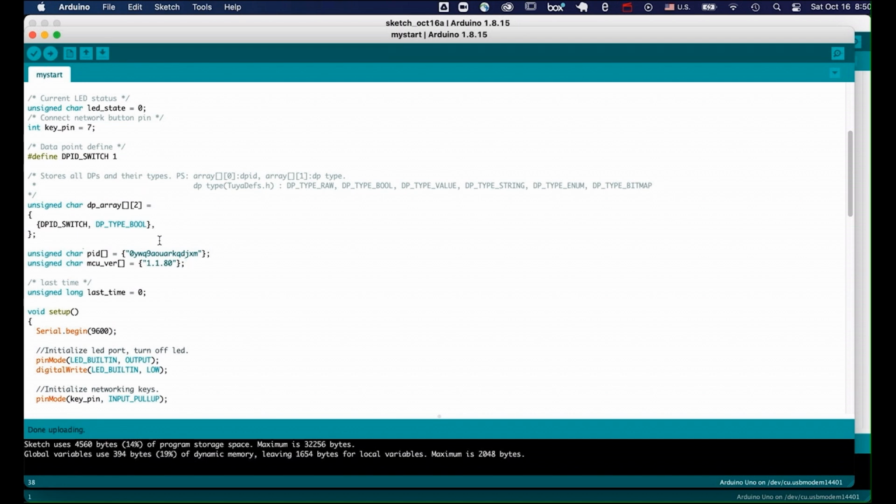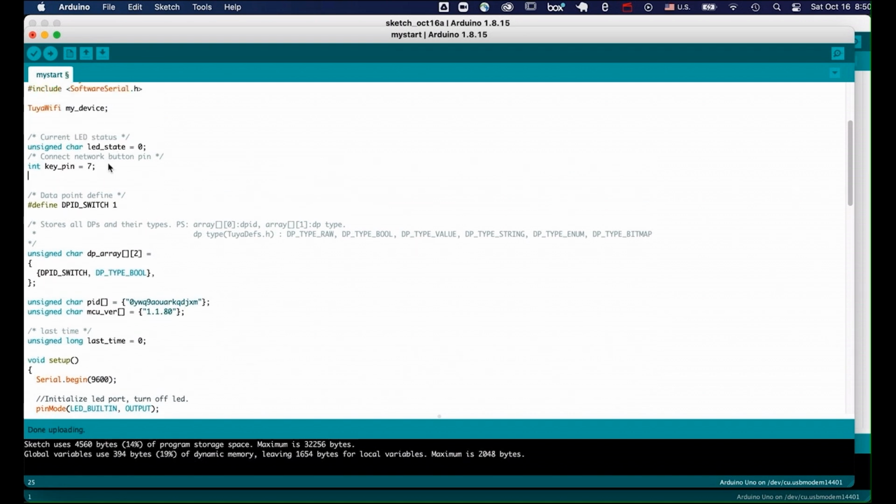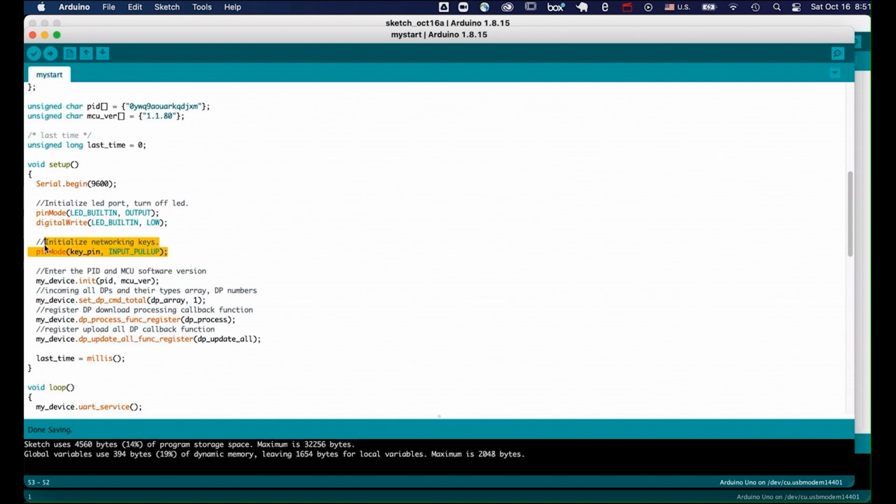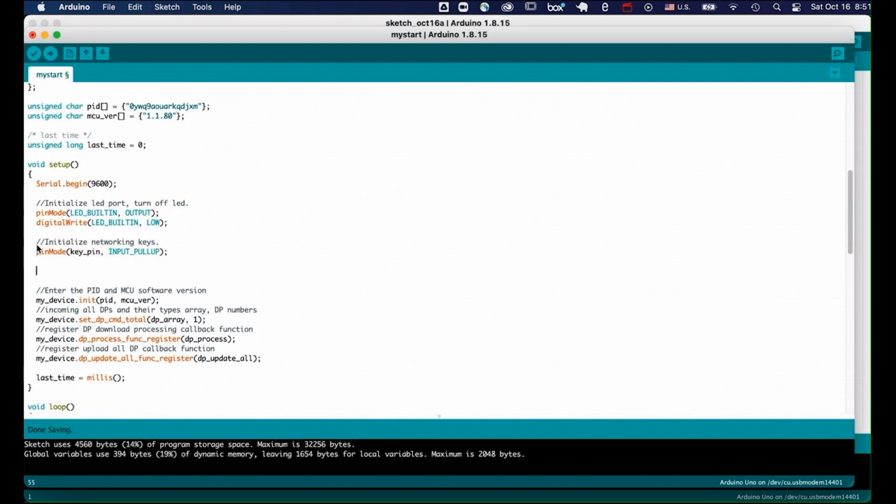All we're going to do is come in right here in our variables. Let's just add one more variable, and let's say this is going to be relay pin. You remember that was connected to pin 10 on the Arduino. Also, while I'm at it, let's make this const as well, because it's not going to change. And let's come down to setup, and let's basically just take this code and duplicate it.